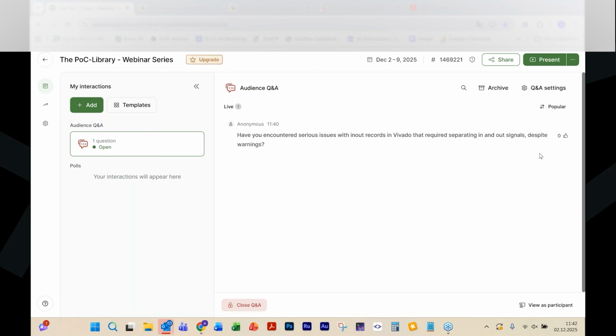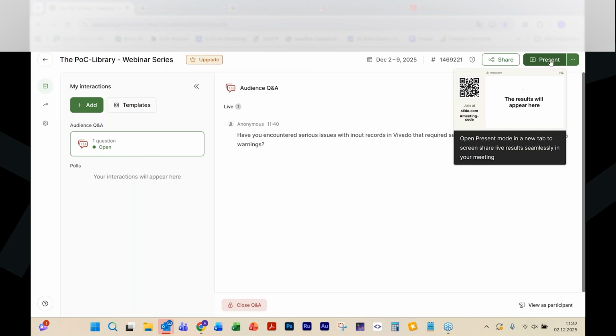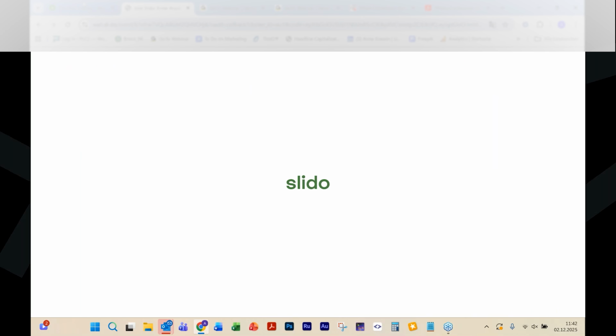Having multiple sources requires you to use resolved data types inside of your record. That's the first thing you need to do. So you're limited to unsigned, signed, standard logic vector, and standard logic data types inside of your record, which is usually for synthesis not such a big problem.